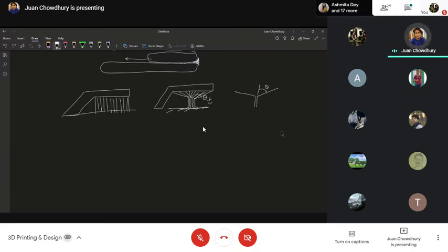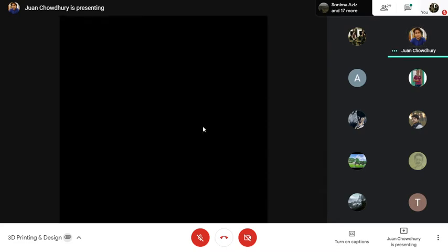Why? Because you are depositing very little material over here, whereas for a full-fledged object you are depositing a lot of material, which creates a good amount of downward weight. In the case of a support structure, this thickness is considerably reduced, which means that the angle at which you can go on printing without requiring any support is substantially low. Yeah, that's a good question. Anything?